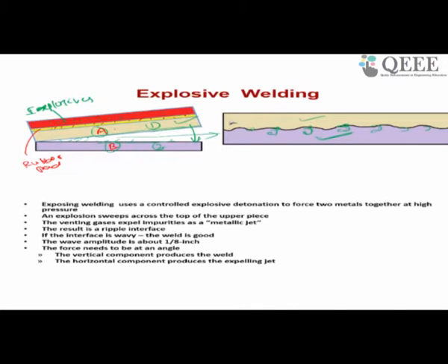Then they do it in a remote place, go to a remote place, and then blast. They explode the explosive. Then aluminum, a ductile material, will come and hit the steel. Then joint will happen like mechanical interlocking. Then what they do? They machine out the bimetallic component, because you want to join steel to aluminum pipes. Suppose you want to get a pipe of 3 mm diameter, 6 mm length, of aluminum steel. Then what they do? They machine from this zone.